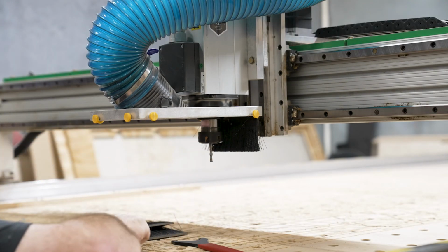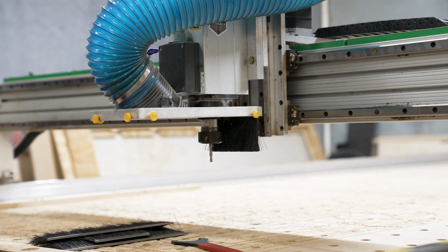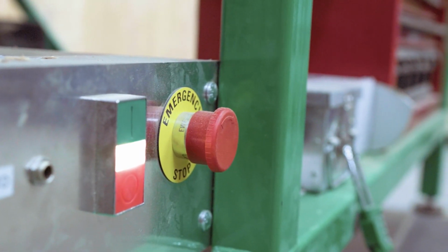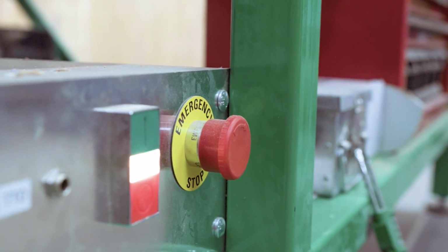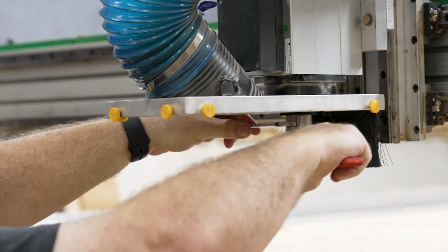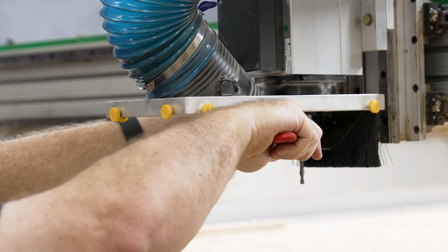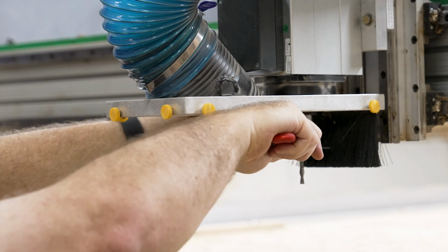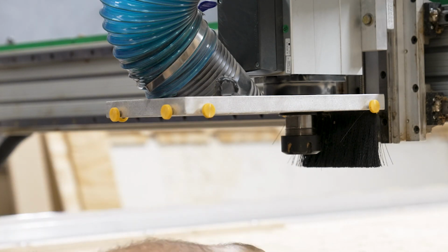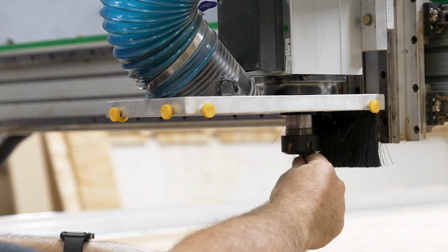One thing to be careful of when you are releasing this nut, so I have it over here for a reason, because if you do this right here, your knee has a tendency to hit that E-stop. If you hit the E-stop, you've got to start over and set the home position. Experience: the one thing to be careful of when you are loosening the nut, notice the height of my hand, and as I pull, I will run my hand into that corner or that yellow nut. Experience, it'll hurt, and it'll gouge some of your skin out.